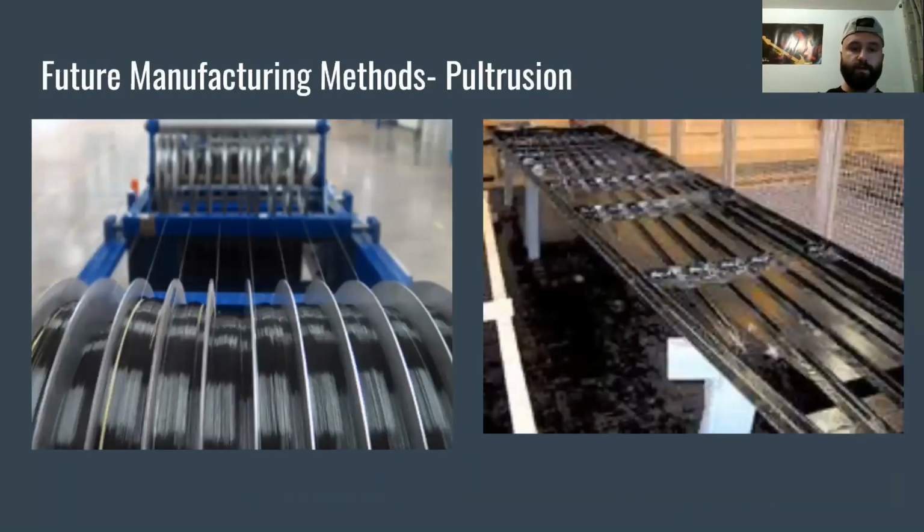So by 2050, we will see the turbine blades manufactured through the pultrusion of carbon fiber. Individual strands of carbon fibers will be pulled off spools to form sheets. These strands of carbon fiber are passed through a resin like the one mentioned prior to form the composite. They will then be placed in a mold and allowed to solidify into the desired shape.